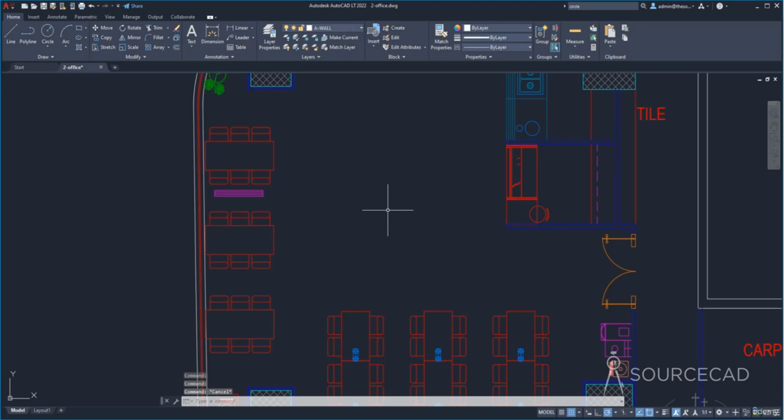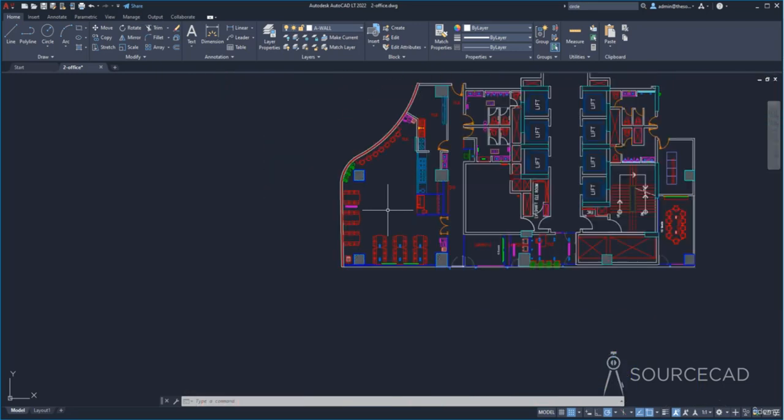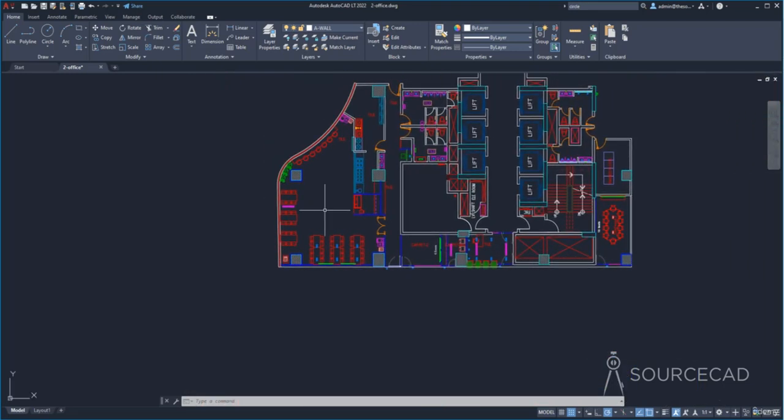Now if you want to select several objects quickly, then you can do that using selection window or crossing window. So now this is what we call selection window. Click anywhere in the drawing area and let go of your cursor. Don't click and hold, just click, let go. Now move your mouse, and this kind of window is called selection window. You'll get this kind of solid window which is blue in color with this solid boundary. Now everything inside this window will be selected.